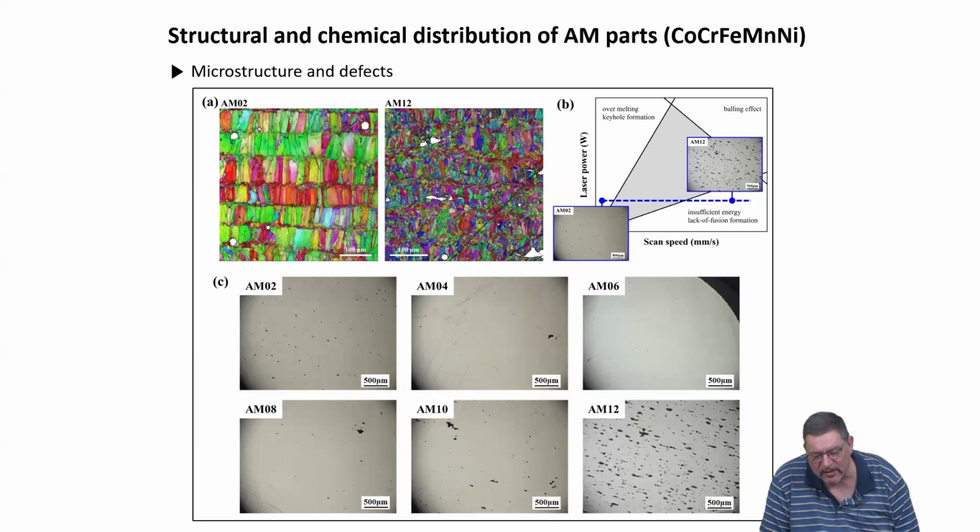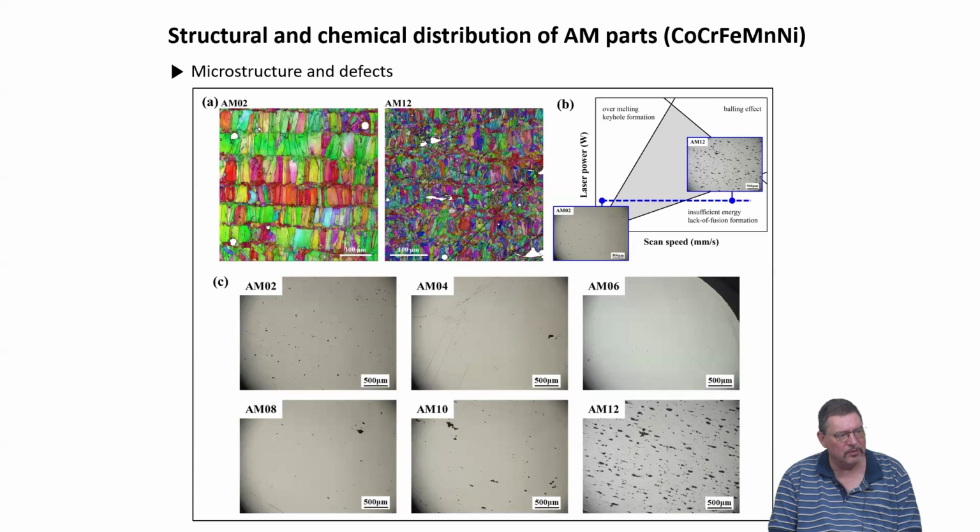And what you see is the typical structure, right? So you see basically in the microstructure the impact of the previous scanning of the laser. This is laser powder bed fusion, which was used here. And otherwise you see a very, very strong anisotropic microstructure as you would expect it for additive manufacture.